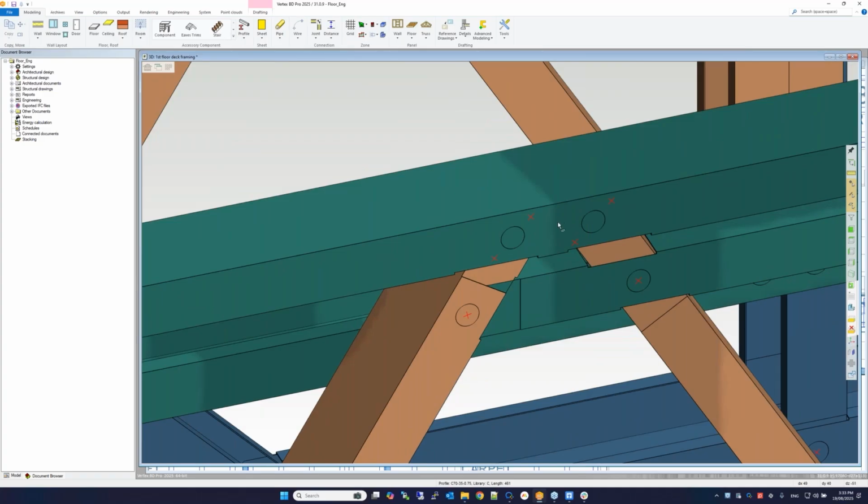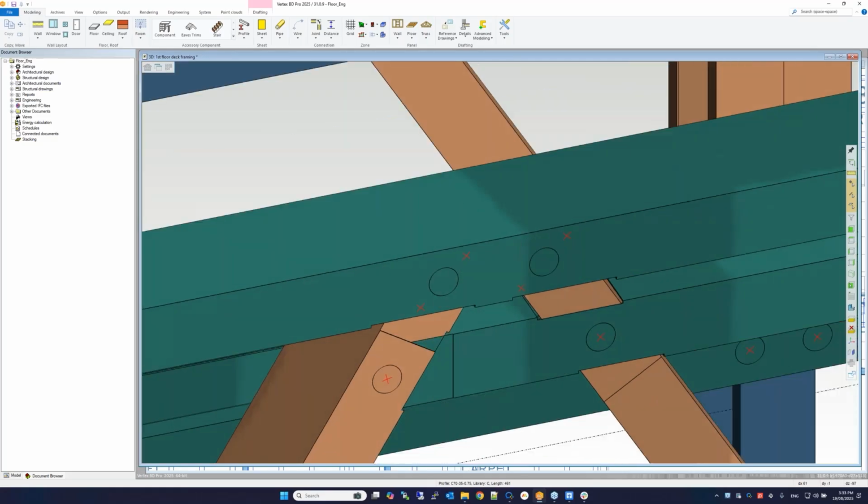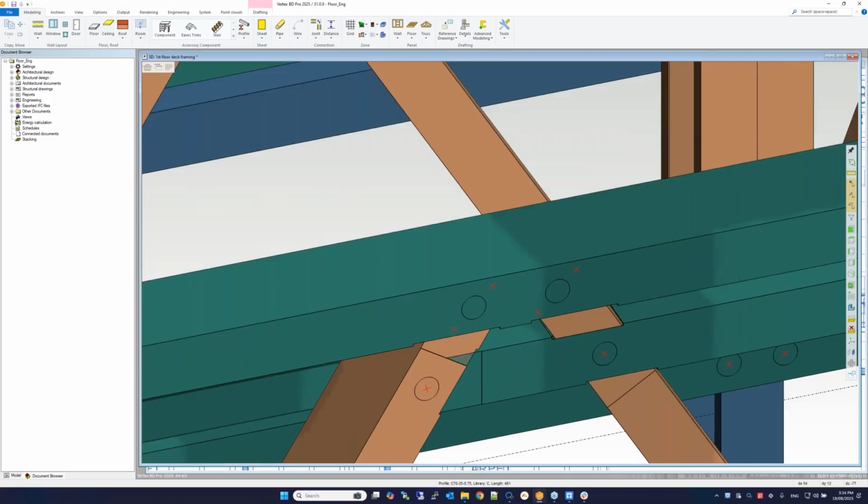That means after the engineering, the software thinks you need two screws here for these joints. So this is a table-based calculation. We can customize, if you have the capacity of any sort of joints, like a bolt or rivet, we can customize that into our software. In the engineering, it will use those capacities for the calculation. But by default, we only have screws.